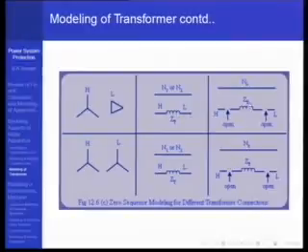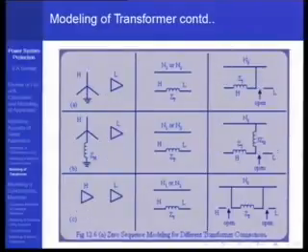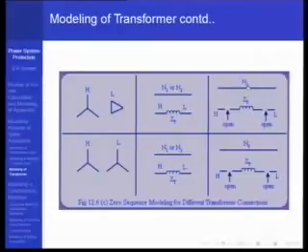It's shown as the same ZC, so it's assumed like a bank of 3 single phase transformers. But otherwise the zero sequence circuit has to be worked with the zero sequence impedance data only, not with the positive or negative sequence. And that's why actually this neutral is also shown different, N1, N2 and N0. Everybody is shown a different neutral, just to emphasize that the ground issue is involved here but is not involved here.